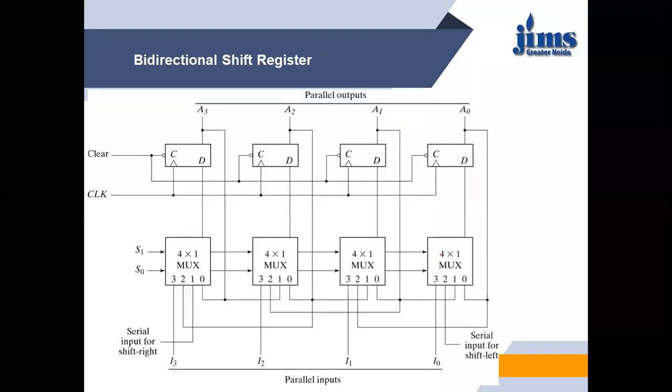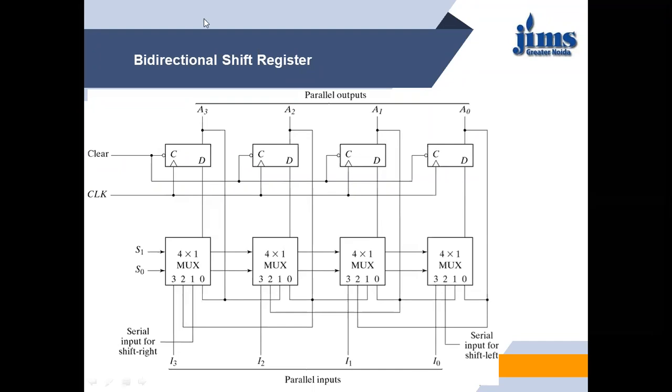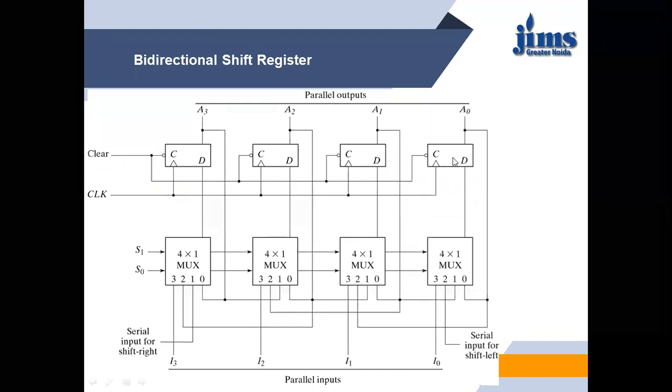So this is the wrong label. This is basically a universal shift register, not the bidirectional shift register. It is a universal shift register. So here we have used 4 D flip-flops. The clock to all the flip-flops is common.